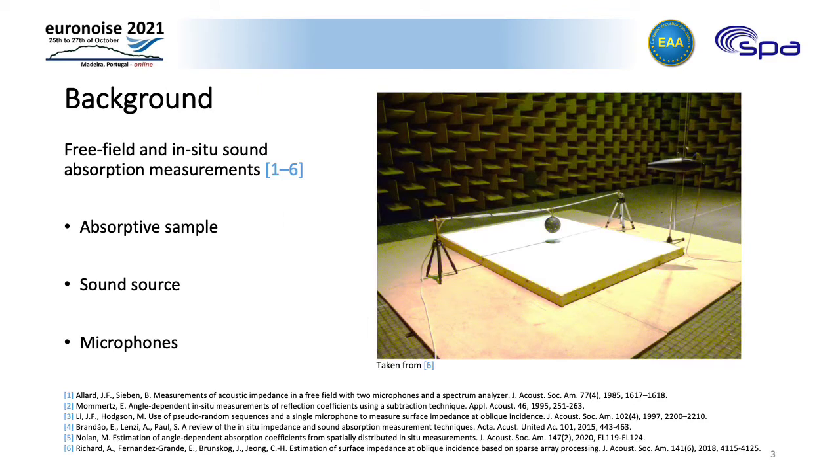In-situ measurements of the sound absorption aim at characterizing the absorptive properties of the material when it is placed for its intended use and location. These methods comprise subjecting the absorber to acoustic waves emitted by a sound source, either omnidirectionally or with a specific incidence angle, and recording the sound pressure at a number of microphone positions. Thereafter, the sound pressure is mapped to the absorption by means of a suitable data processing method. For instance, plane wave decompositions, spherical wave decompositions, etc.